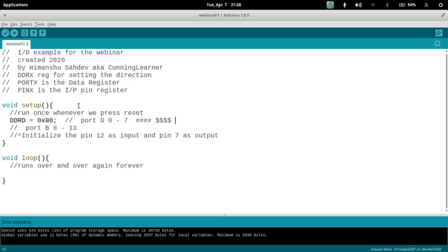So I can also write 1 left shifted to 7. But wait, this is a very bad way of writing 1 to a particular bit, or setting a particular bit, because we are writing just a 1 on bit 7, but we are also writing zeros to other bits, so we are affecting other bits.